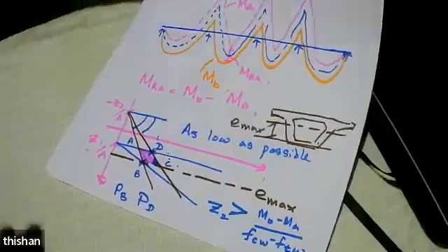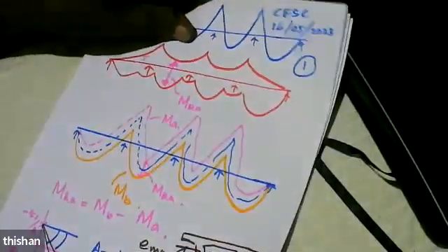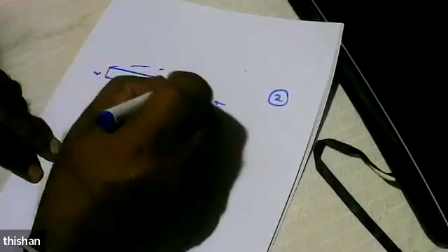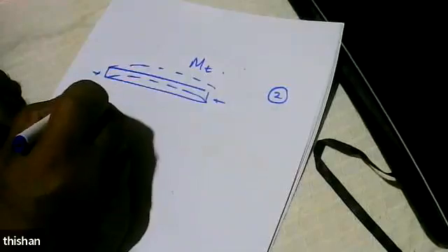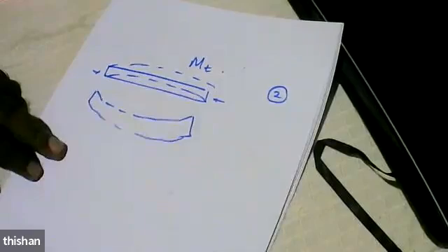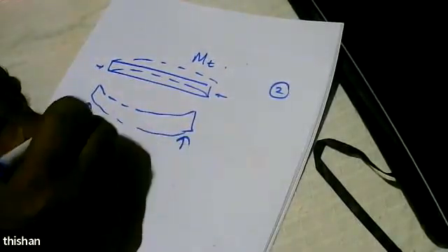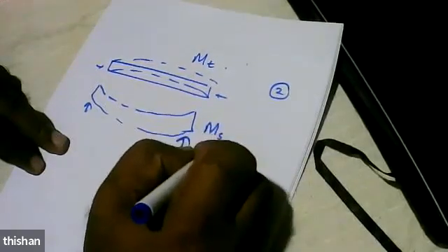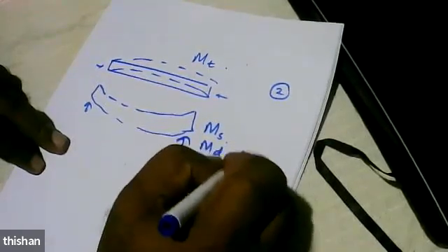So basically, for the simply supported case, we have a beam subjected to pre-stressing. Then it will move up like this. We call it moment at transfer. Then it will bend like this when it is subjected to the maximum loads. And we say it is the service conditions where MD and ML will act.